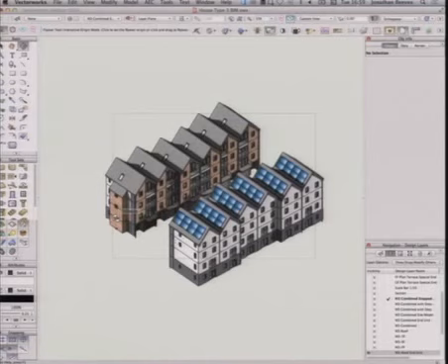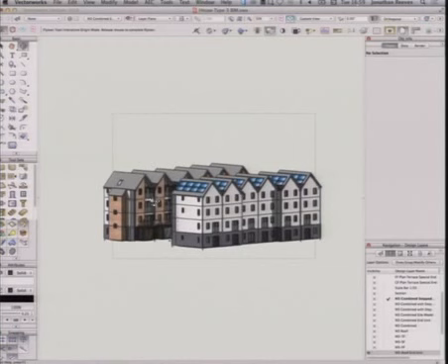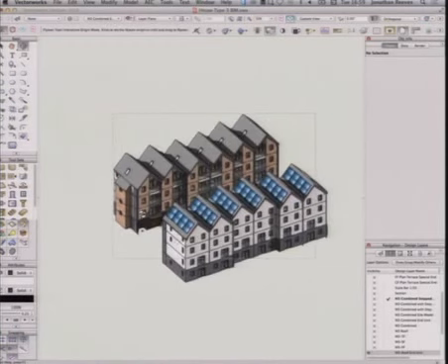They're not sheet layer viewports just for creating the drawing. You can see I'm able to modify and spin around. It's a fantastic opportunity if you're doing large-scale developments, say 500 houses. You might have 10 different house types, model each one up in a separate file, reference it into a site plan, viewport it around the document. Then if you need to update house type A, you just update. All house type A's around the site will update immediately. And it works very, very well dynamically.